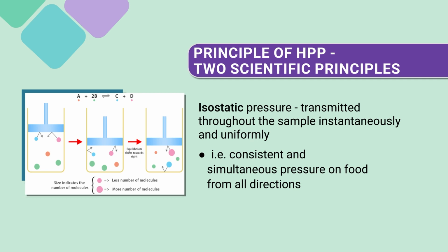It is actually what is happening inside the system. Adiabatic heating is taking place, due to the heat of compression. The pressure is being applied, so what is the heat of compression causing? Causing the rise in the temperature. Though we call it non-thermal, there could be a significant rise depending on what pressure we are going to. So gradually we are increasing pressure, it also leads to the increase in temperature.